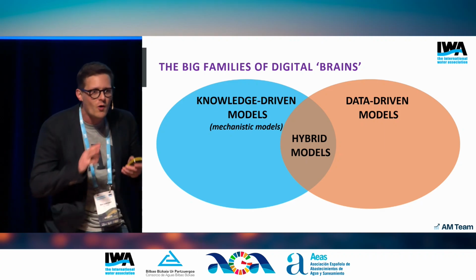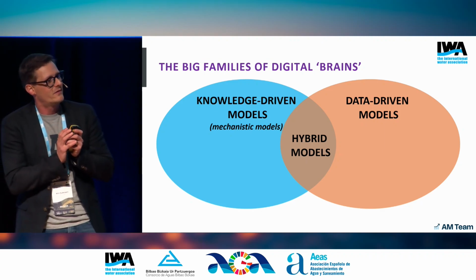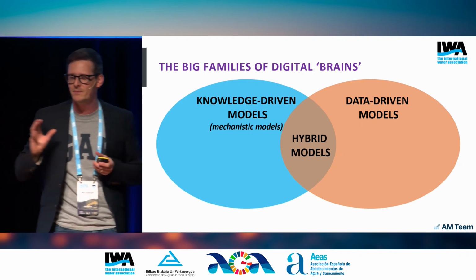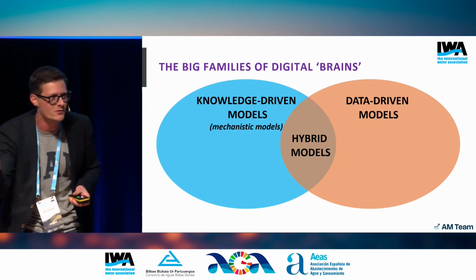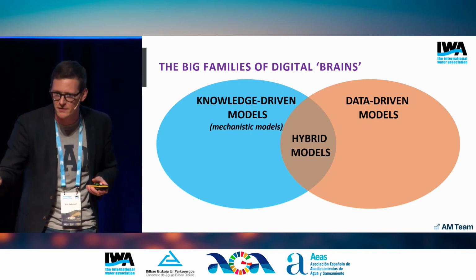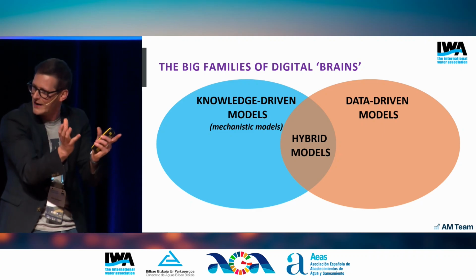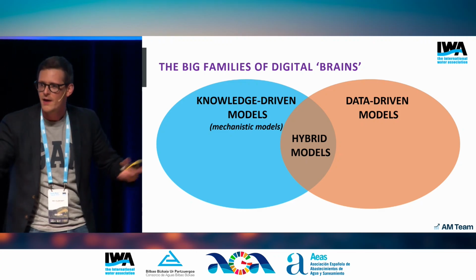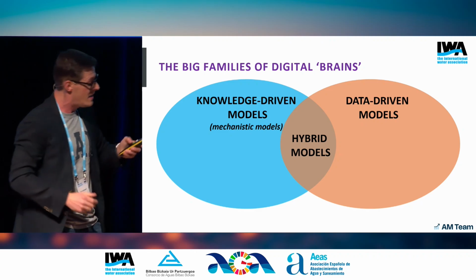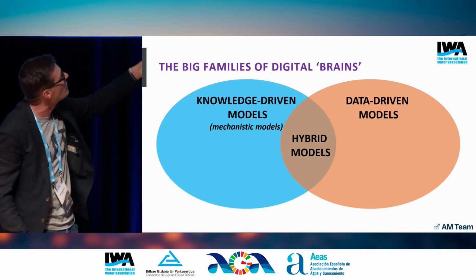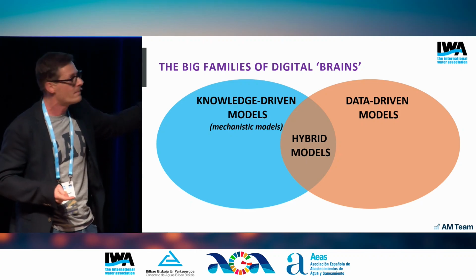When we look at the core of digitalization, for example, a smart treatment plant, the core of it, compared to a conventional SCADA system, that exists for decades, right? You send some sensor data to a SCADA or to a PLC, and you do an action. What is the big difference is that you bring in an additional layer of intelligence, a model, an artificial brain. Can be AI, can be a mechanistic model. And actually, these are the two families of models. Not very well understood, but crucial to understand.